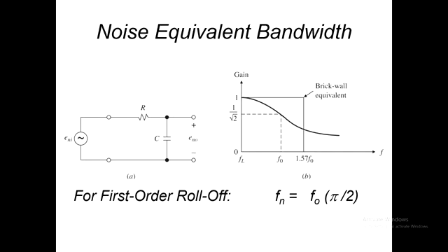It will be attenuated, but because it's wide bandwidth, and unlike signals like my boring voice, which is band limited in itself, my voice doesn't extend out to infinite frequency, although some might think so. It tapers out. However, the noise doesn't taper out of its own accord. Well, it does, and as I said this morning, that's in the vein of terahertz, way high frequencies. So that is an ever-present noise that will contaminate signal. And if we can deal with that somehow, or know how to treat it, that's good.